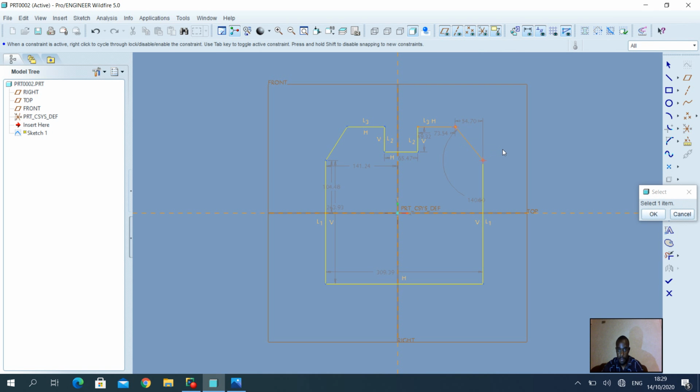Actually, the wheel of the mouse, I'm going to be clicking here to get the vertical distance of that. And here it is. We have this vertical distance, and once I assign this one, the angle automatically vanishes away because the software respects my dimensions more than the automatically assigned dimensions of the software. So I'm going to be also putting the horizontal distance right here.